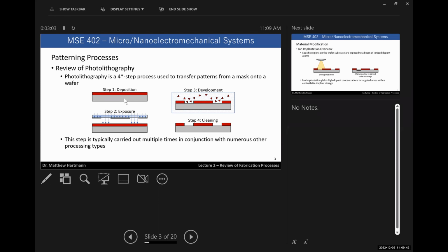So anyway, during the deposition process, you effectively put your wafer on a spin chuck, put a little bit of the photoresist, like pipe it onto the surface of the wafer, spin it at several thousand RPM, depending on the thickness of the resist that you want, and it makes a nice, even, uniform coat, or at least hopefully it does. Prior to that, you might have to put a primer like HMDS on it to help the photoresist stick and things like that.